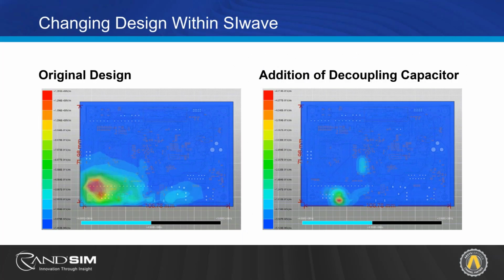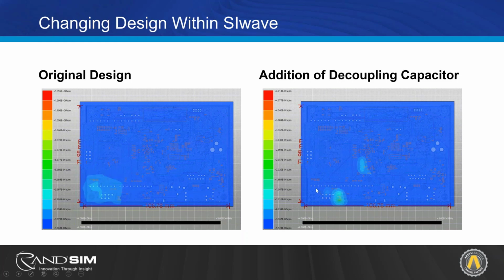And that's what this is showing here. I can very simply, in that region, click on a spot that had the power plane present. I drew a little port that I said I want to create a decoupling capacitor for. I assigned that to 10 microfarads, and I reran my decoupling analysis.